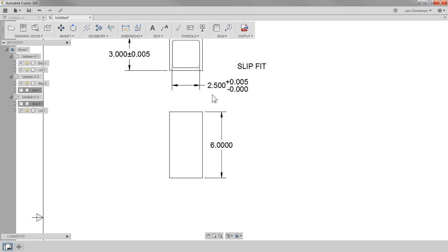The last thing I want to show you is something else. I'm not trying to make this more confusing than it already is. I hope this is not too confusing. But there are also a couple of other questions you should ask. Another one would be, what kind of surface finish do you want this to be? Because I can actually make something within tolerance, but it has a very rough surface finish. So there's a symbol up here where you can add a surface texture to it.